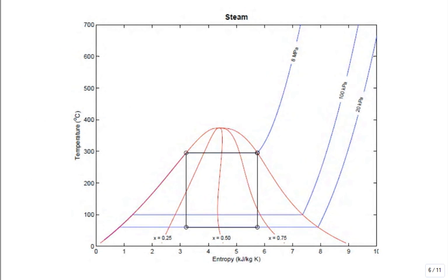Let's show it on that temperature entropy diagram. Well, the Carnot cycle is simply a box, a rectangle. The Carnot cycle goes like this and around. So you can see it's at 8 megapascal, 20 kilopascal. Is all of the heat brought into the Carnot cycle all at this high temperature of just a shy bit under 300 degrees C?